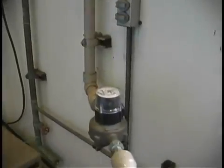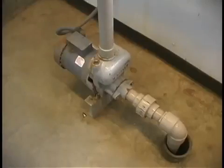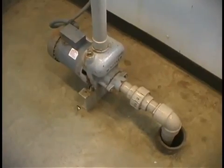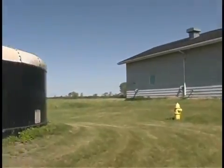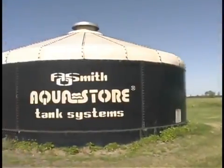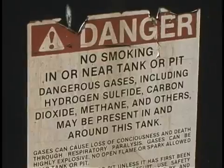The spent filter backwash water is held in a retention tank below the plant. The decant off the holding tank is recycled to the plant. The sludge is pumped to a dewatering tank. The sludge is hauled to a non-hazardous landfill at the rate of about 20 cubic yards every 2 years.